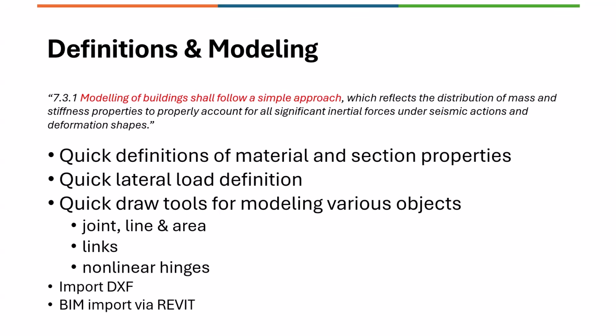Similarly, we also have drawing tools, starting from simple joint, line, and area that can be modeled: joints for joint loads or restraint assignments, lines for beams, columns, braces, and areas for floor slabs and walls and foundation rafts, etc.